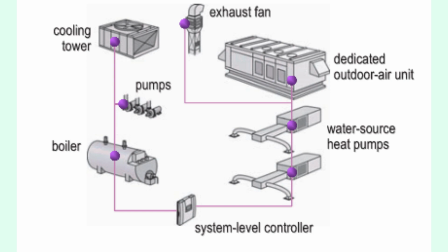Examples of system-level control: chilled water, VAV system, coordinates air handler, terminal units, chiller, and boiler. Packaged rooftop, VAV system, integrates all functions in one unit. Fan coil, chiller system. Uses outdoor air reset and changeover deadband, 15 degrees F, to save energy. Water source heat pump system. Maintains loop temperature between 60 degrees F and 90 degrees F using tower and boiler.